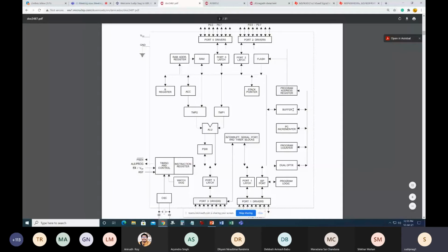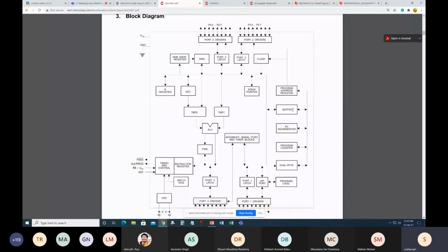Now, what do I mean by loading over here? Recall what is fan out in digital circuits. Fan out means how many inputs of similar gates can be connected in parallel to the output of one logic gate. Okay, so look at the definition, revise it. Fan out means basically there should be a maximum limit up to which I can load the output of one of the gates. Why does that maximum limit exist?